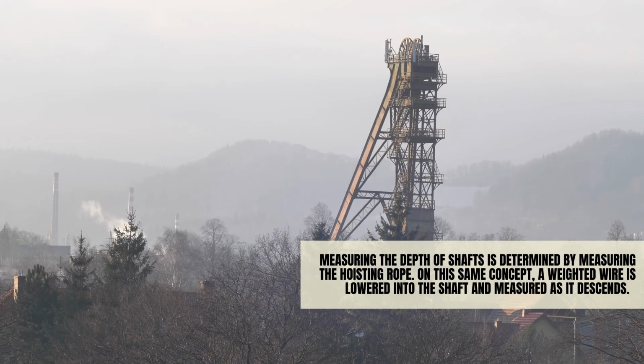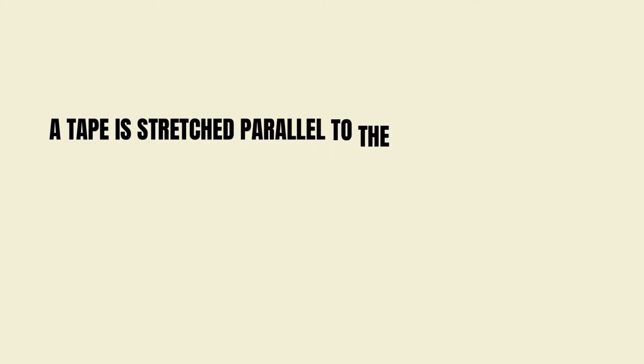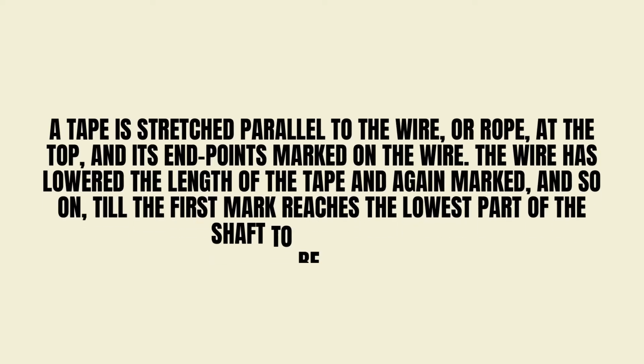The depth of shafts is determined by measuring the hoisting rope. On this same concept, a weighted wire is lowered into the shaft and measured as it descends. A tape is stretched parallel to the wire or rope at the top and its endpoints marked on the wire. The wire is lowered the length of the tape and again marked, and so on, till the first mark reaches the lowest part of the shaft to be measured.